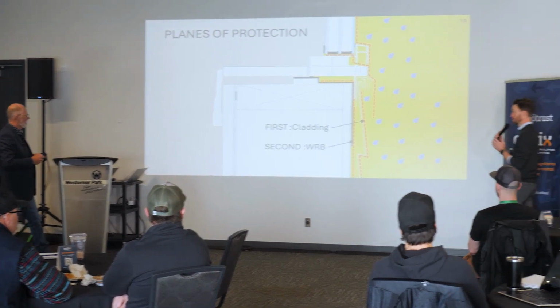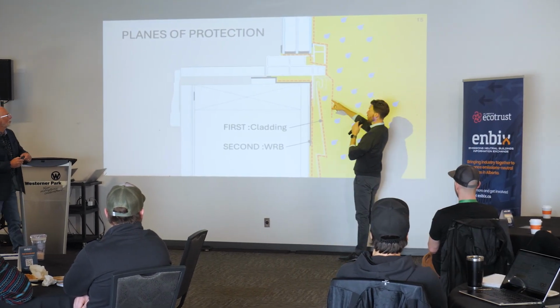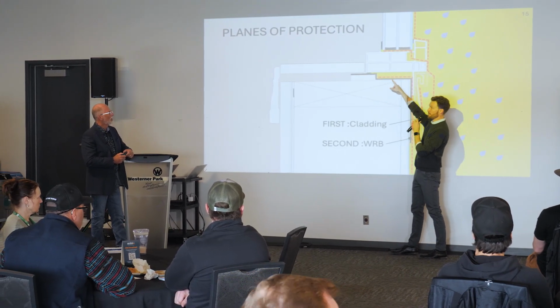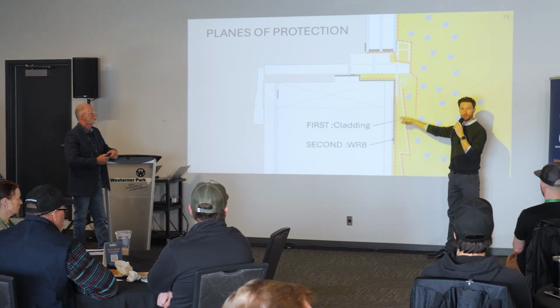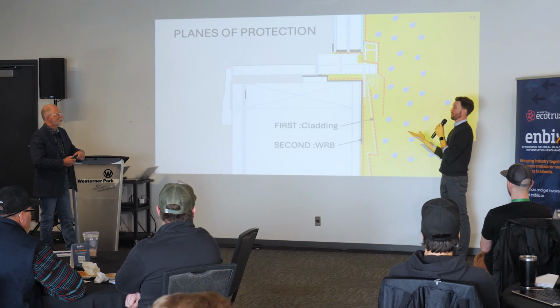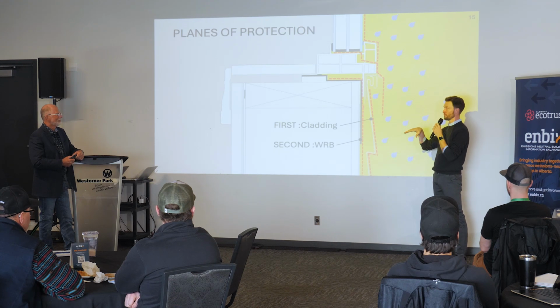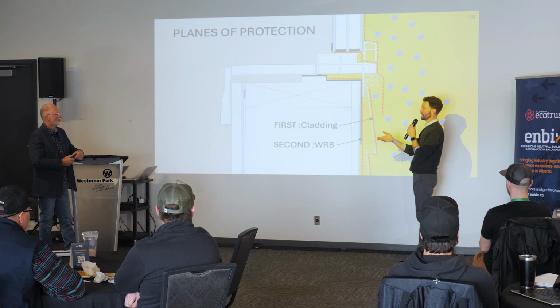The other thing is if we do get a bit of condensation in here, and this is a sealed sill with a back dam that's impermeable to water and drains to the outside, do we care? So it's really a low concern there, unless you put something in there that becomes food for mold, like the wrong kind of insulation. Right.